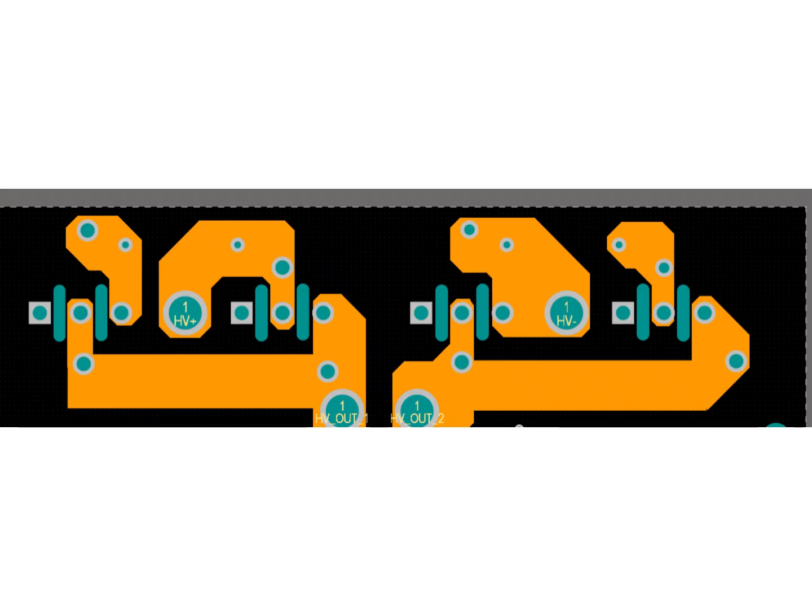High current routing philosophy. For high current paths, the PCB layout follows a different design approach. Wider copper tracks, reinforced current paths, and thermal considerations are intentionally incorporated to support inverter-level power handling. H-bridge midpoint track design. The H-bridge midpoint track, which carries the inverter output current, is designed with an approximately 7 mm wide copper trace on the PCB. This wide trace helps reduce resistance and limit temperature rise during high-load operation.